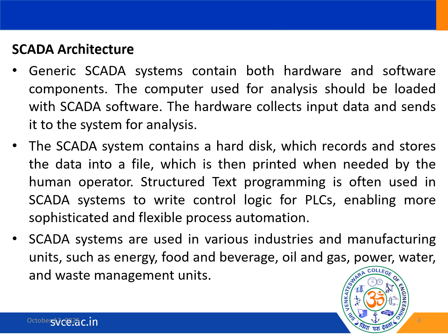Next, moving on to SCADA architecture. Generic SCADA systems contain both hardware and software components, and here we'll be learning about the SCADA architecture. This hardware and software is used to monitor and control industrial operations. The software is installed on a central computer and handles all the data analysis and visualization, while the hardware interfaces with the sensors and field devices used to collect real-time input from the physical process.